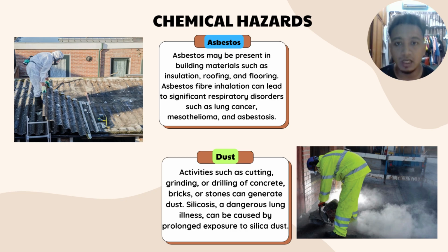For asbestos, asbestos may be present in building materials such as insulation, roofing, and flooring. Asbestos fiber inhalation can lead to significant respiratory disorders such as lung cancer, mesothelioma, and asbestosis. So for the dust, activities such as cutting, grinding, or drilling of concrete, bricks, or stones can generate dust. Silicosis, a dangerous lung illness, can be caused by prolonged exposure to silica dust.